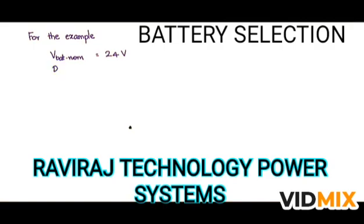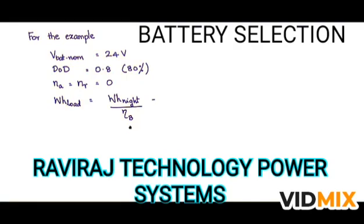So V battery nominal is 24 volts, DOD 0.8, which is 80% depth of discharge. NA is equal to 0, that is number of days of autonomy, number of days of recharge. We will set it to 0 because we are designing it such that the photovoltaic panels are participating in supplying to the load every day. Watt hour load is watt hour night load by efficiency of the battery, which is equal to 914.4 watt hours by 0.7. I'm taking 70% efficiency for the battery, which is a practical value. This turns out to be 1306 watt hours.